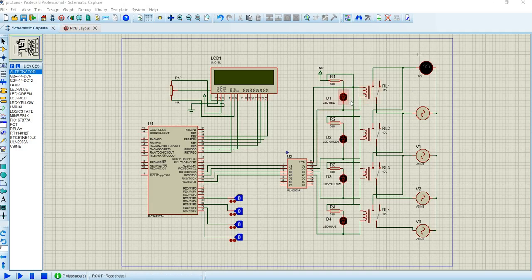So that will be represented with the help of these LED indications, and the selections will be done through these electromagnetic relays. So these are the connections made to the microcontroller, and this relay is getting switched through this ULN2003, which is the driver board to control the relays from the microcontroller, by getting input of signal 12 volts and providing that signal to the relay boards based on the trigger pulse from the microcontroller.